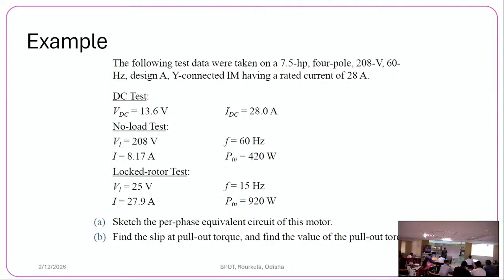You have the stator voltage and stator current. Here you have the magnetizing branch. The magnetizing branch we don't show, because we apply only a small voltage to get the rated current. So at that voltage XM is not required. So here you have R2 dash and X2 dash.